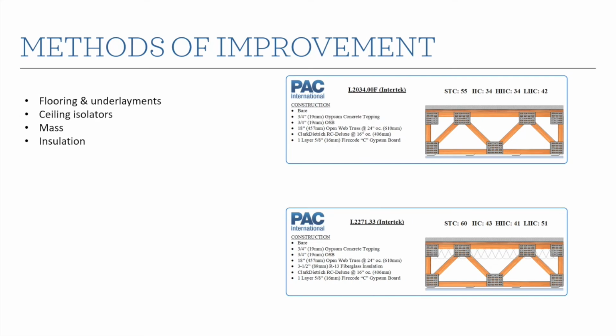Insulation is another thing that we can use. And if you think about going into some sort of modern design fast food space or something like that, right? It's all hard surfaces, polished concrete floor, gypsum board walls, a lot of glass, exposed metal deck, right? All hard surfaces. It doesn't take many people talking in there for that sound to build up really quickly. And what happens is there's nothing to absorb that sound energy, so it just hits the walls and it keeps bouncing off. We've got this big reverberant space, the sound just builds up in it.